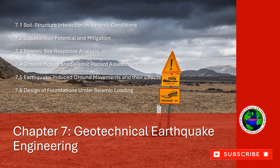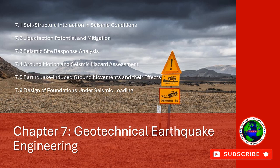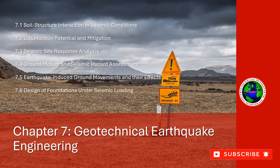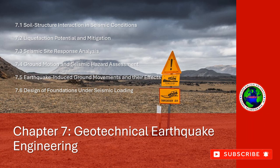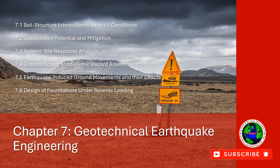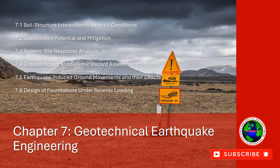4. Seismic hazard maps. Seismic hazard maps provide a geographic representation of seismic hazard across a region. These maps typically show the expected level of shaking, e.g., PGA, spectral acceleration, with a given probability of exceedance over a specified time period. Seismic hazard maps are often used for land use planning, building codes, and risk management.